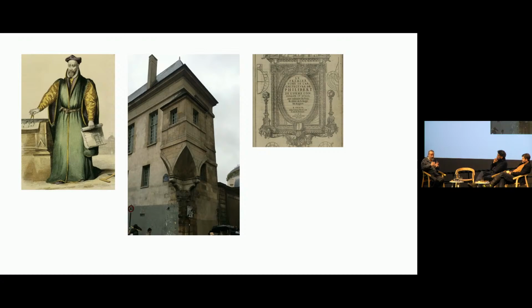and know how to extract not only in small bits of stone, but also in the number of phases of shaping your stone. Because shaping stone is going to take you from 1 to 20 or 50 different phases to get your stone shaped. And you want it to be as efficient as possible. So you want as little as possible of what we call templates to shape that. So in fact, these little vaults, cantilevered, are just 150 to 200 mil thick. So again, this architecture is driven by the material and the cost associated to it.